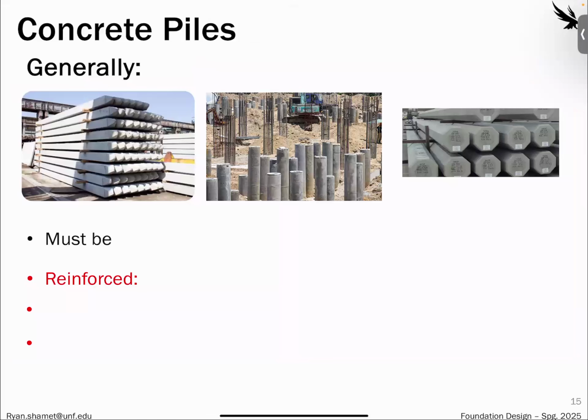Okay, so for concrete piles, generally these are going to be precast or cast in place. Or bored piles. So these are where you could have a weird geometry or something where you're augering down and then you're boring it. So with these piles, if they're driven, they can't be vibrated in, they must be driven.